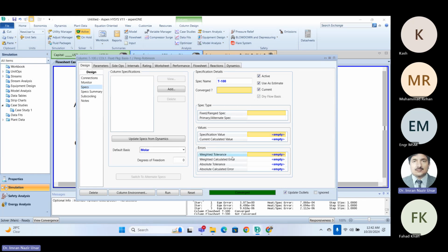But if you define your values, then the solver will work accordingly, and some mishap could happen, because their internal settings are very robust. If you have proper knowledge, then you define. Otherwise, empty values are very good, because at least we are getting some convergence. For example, absolute tolerance, if I say it is 0.001, maybe this value is workable, maybe not.